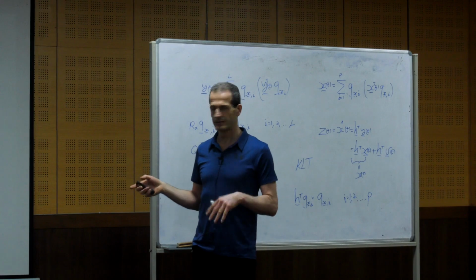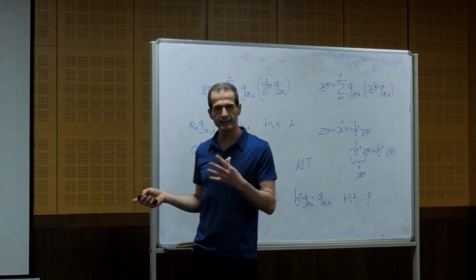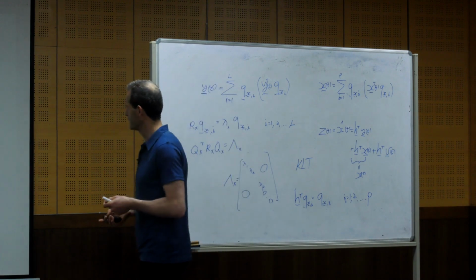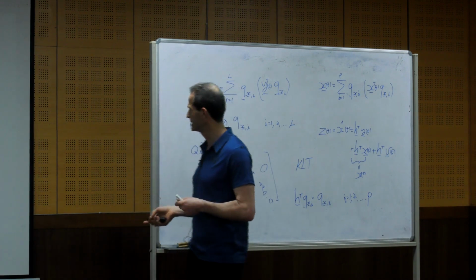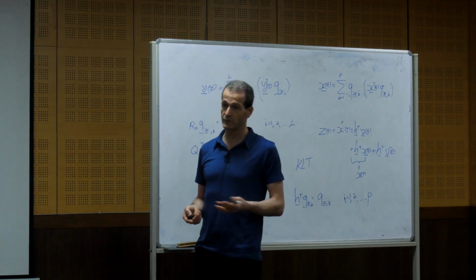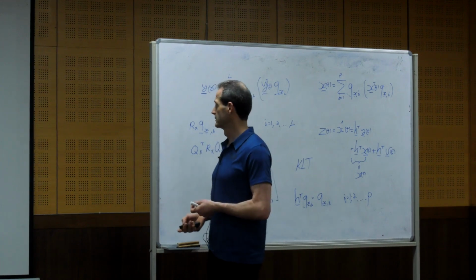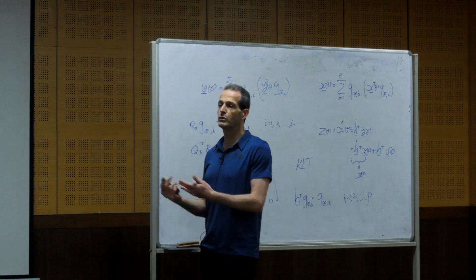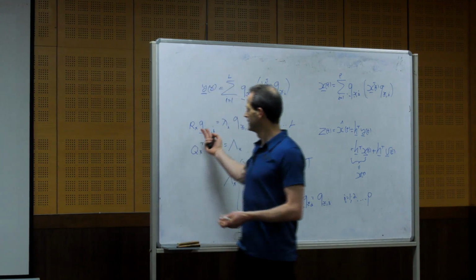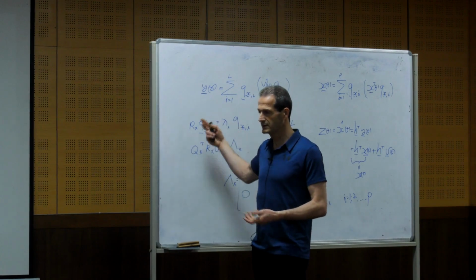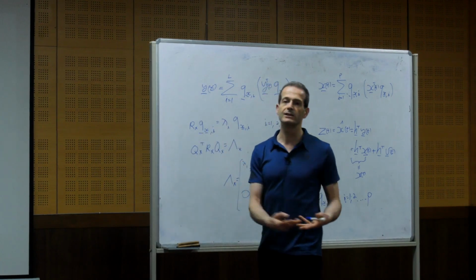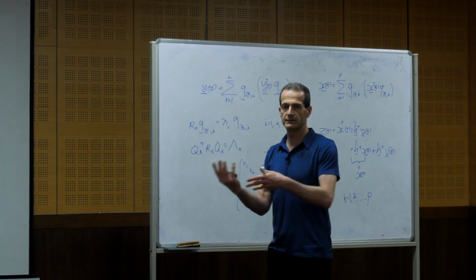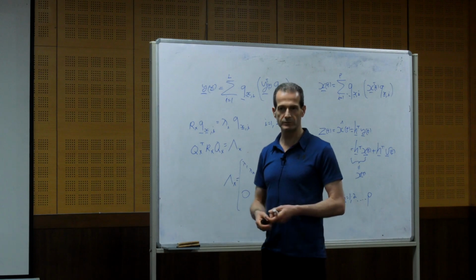The reason behind it, and the understanding, is very similar. That's why we use the short-time Fourier transform for many non-stationary signals, or another transform, which can be the discrete cosine transform or other transforms, because we want to sacrifice some performance by reducing the computational complexity using existing fast transforms.